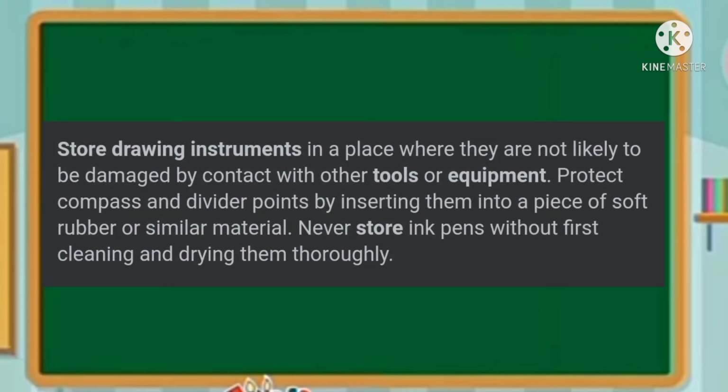Proper storage of technical drawing instruments. Store drawing instruments in a place where they are not likely to be damaged by contact with other tools or equipment. Protect compass and divider points by inserting them into pieces of rubber or similar material. Never store ink pens without first cleaning and drying them thoroughly.